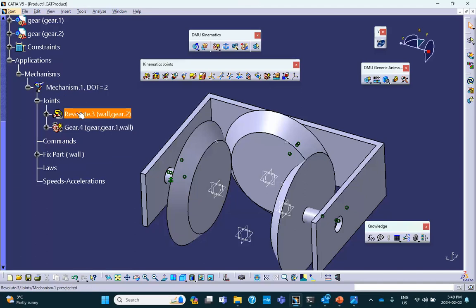Now, we also need, notice that this revolute joint got gobbled up by the gear joint. So I can make another one and then create a gear joint between that revolute joint and this one that's still sitting there, or these roll on each other. So why don't I do a roll curve joint instead?